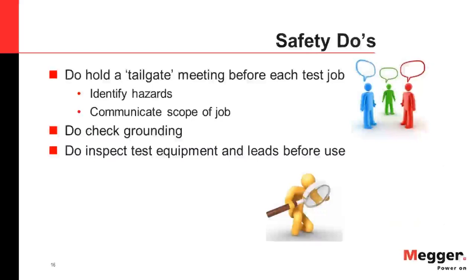Do check grounding. The asset under test should be grounded well. And do inspect test equipment and leads for damage or excessive wear before use. Do connect the ground lead to the test instrument first before any other connections, and remove it last when testing is complete. Do make it a habit to touch each terminal with a grounding stick before moving test leads to discharge any potential stored charge which may be present.